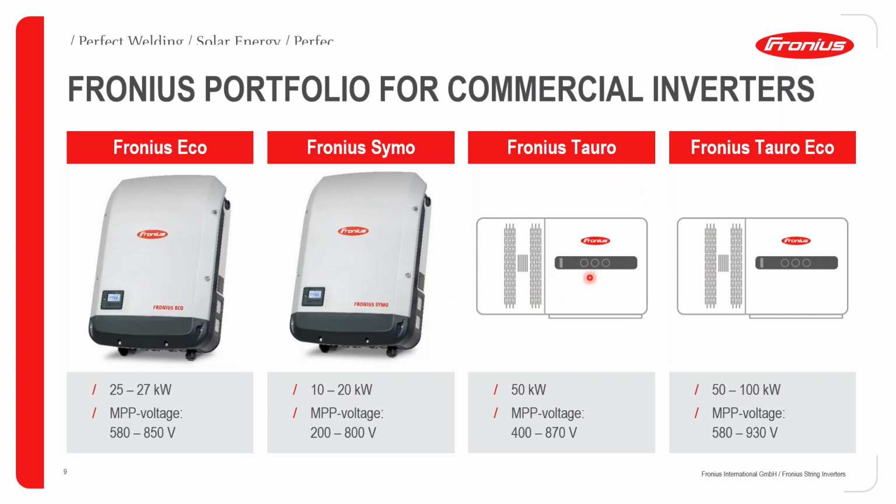Then moving on, we're also going to have a look at the Fronius Taro. This is a 50 kilowatt inverter, and your MPPT voltage range is between 400 to 870 volts. Then looking at the Taro Eco, this inverter will either come as a 50 or 100 kilowatt variant, and your MPPT voltage range will be between 580 and 930 volts DC. Remember, all of these inverters can have a maximum of 1000 volts DC per string.